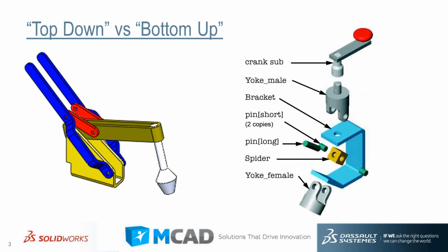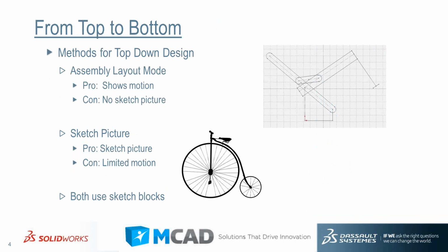Versus bottom-up assembly modeling. Now on your right there I have an assembly that was put together with components that were already designed outside in their own component files inside SolidWorks SLDPRT files, and they were brought together using assembly mating relationships to create the overall assembly. Now the part on the left, it's a hold down clamp, and it was designed actually using top-down assembly modeling, which means that everything was created in context for the assembly. So let's go ahead and get started here, and let's talk about the differences here.